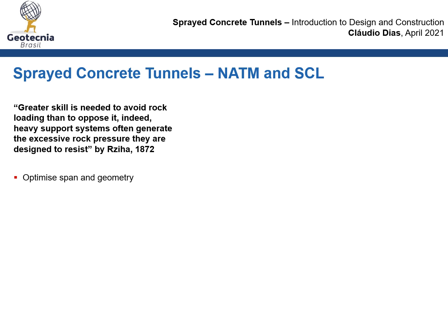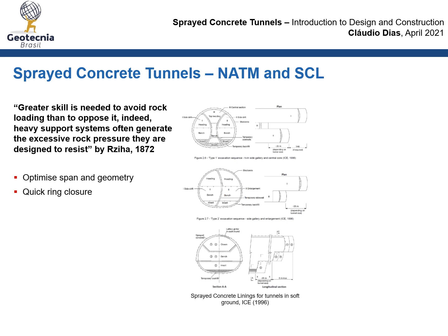It's very important also in these methodologies to optimize spans and geometry, making sure that the geometry is as circular as possible, with a quick ring closure, as we saw in the previous slide. This image here shows different face splits to make sure we are reducing displacements and stability issues with the excavation.